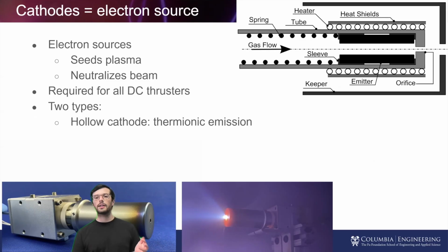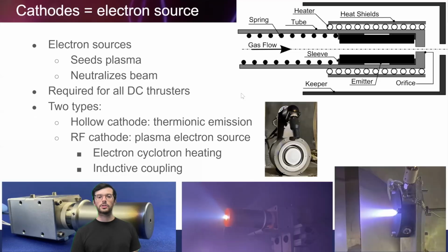So now we have a plasma floating around here. And because we're flowing gas, that plasma gets kind of kicked out. And really what's getting kicked out is the electrons because the ions are getting sucked into here. So you're making a little plasma in here, and then you're flowing your gas out, and that is creating your electron source for your thruster.